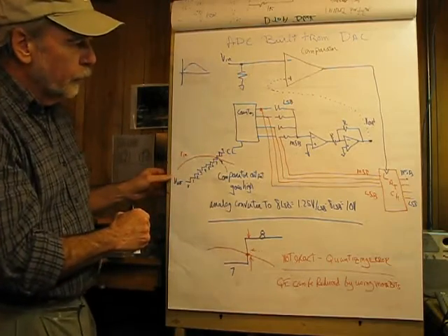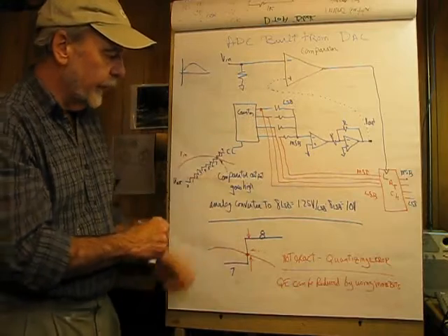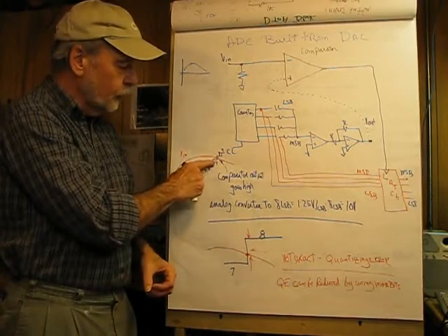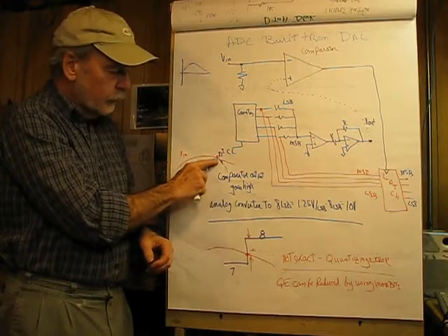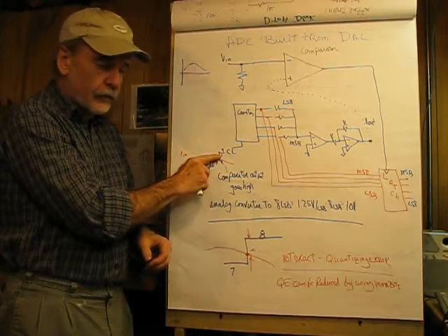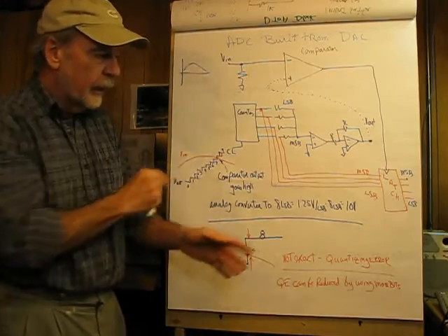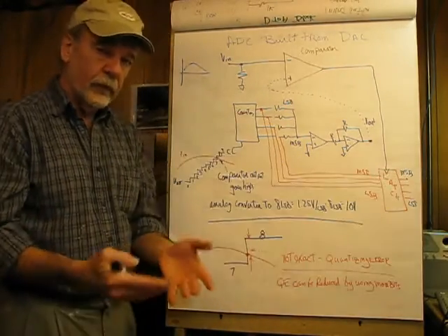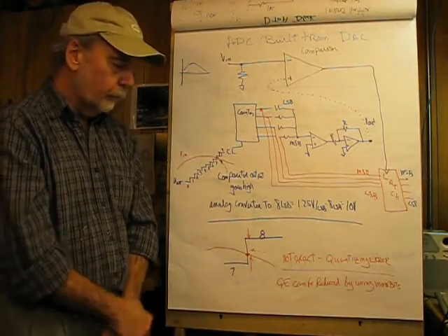And when we do that, the crossover point, the value of the actual count that's producing this, in this case it would be 8, because it crossed over between 7 and 8. So this would latch 8, binary 1000, as being the binary equivalent of the actual input voltage. So that's kind of nice.